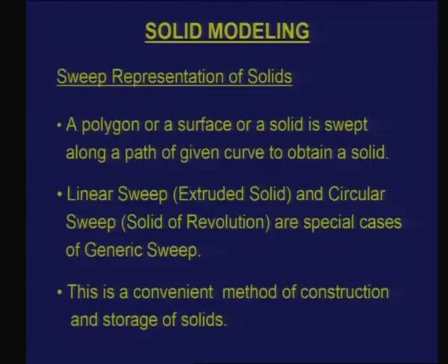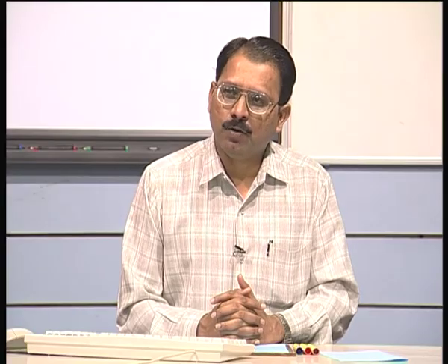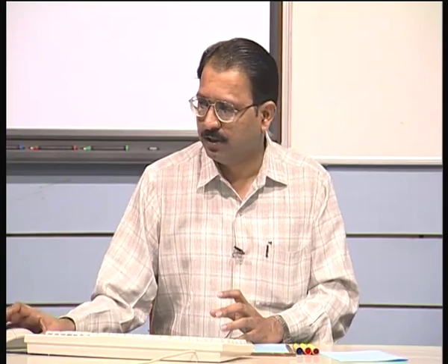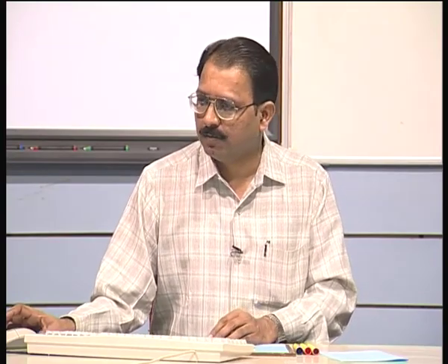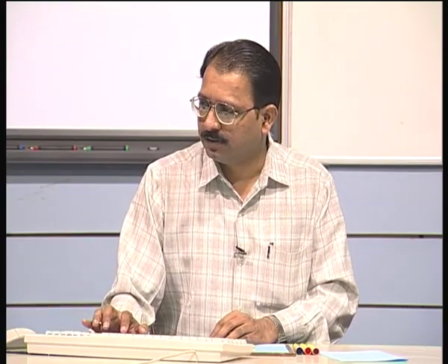It is also easier to store. That is because I have to store basically what I am trying to sweep, a polygon or a surface or a solid, and also the path along which it is swept. If I am able to store these two, I have stored the entire solid representation. From these two inputs, I can generate other representations, or I can display the object. So, I can do many things as far as sweeping is concerned. Sweeping is a logical extension of what we discussed for curves and surfaces.